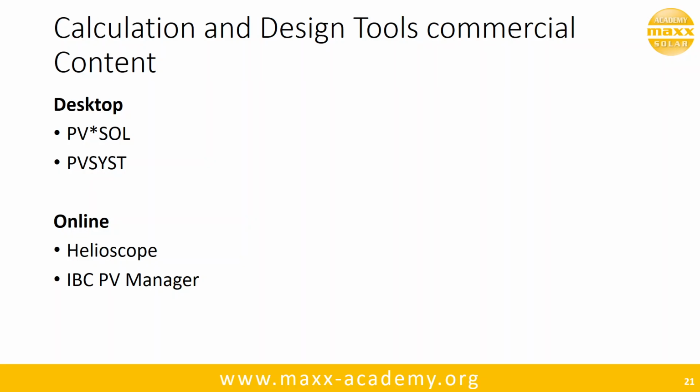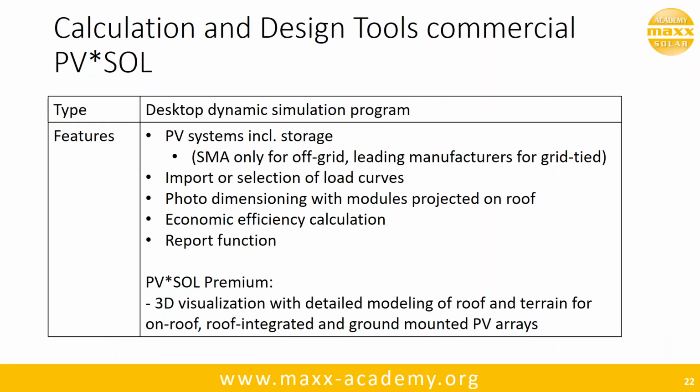Great, so let's start off with PV-Sol. It's a dynamic simulation program. Basically what that means is you see a roof, and you draw the dimensions of the roof in the application. Then you add your panels and the orientation and inclination, and it compares that data together with what inverters you used, and takes the weather data over the years and simulates how much energy will be produced on that specific system.